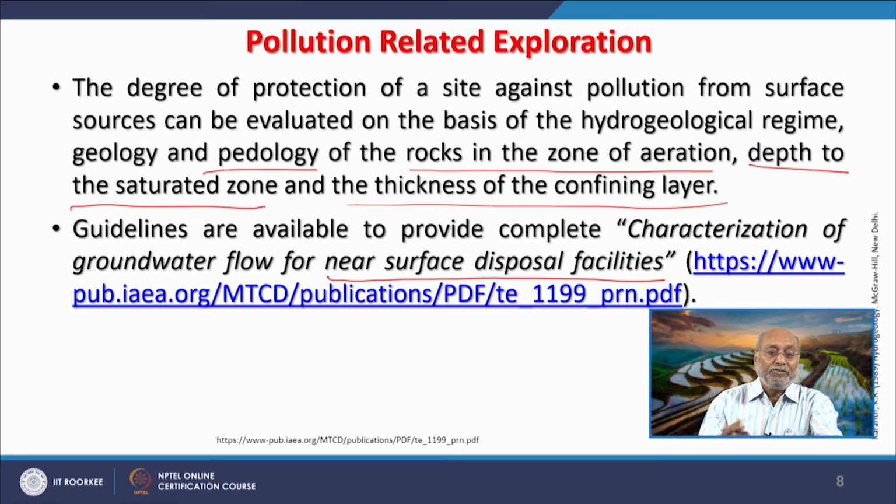So, then research was done on how this ash can be used. People found that if 10%, 20% is mixed with cement, which is now being done, it will not have any strength problem for the cement. So, many cement plants in nearby places started taking fly ash and putting it in the cement. Similarly, when we started constructing concrete roads in the country, a lot of fly ash is being used for that also,